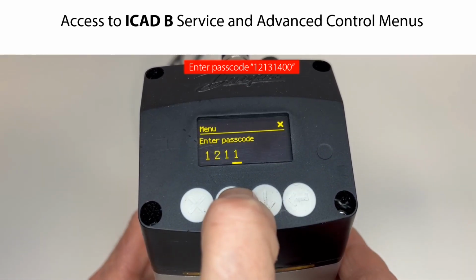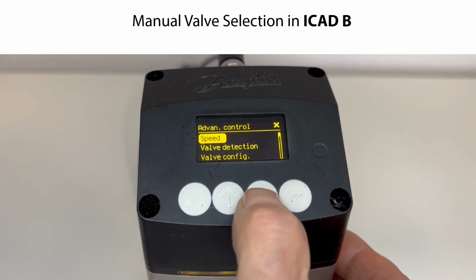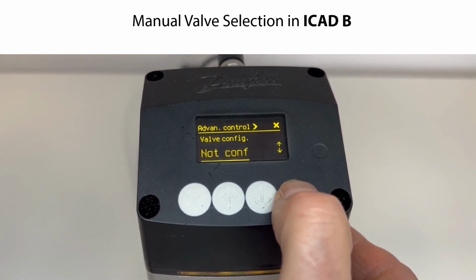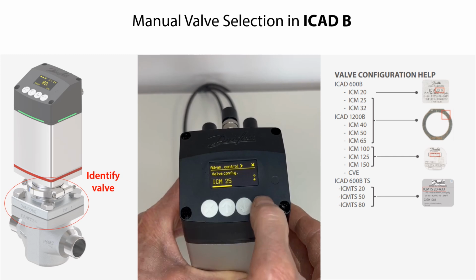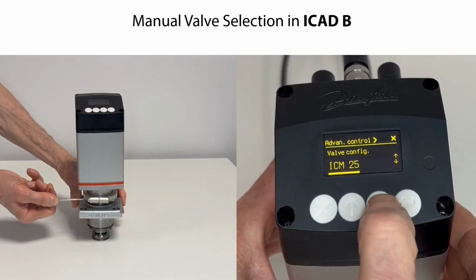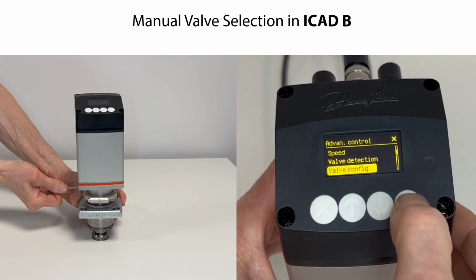If requested, then enter the service passcode as explained earlier in this video. Scroll down to Advanced Control, then press enter. Scroll down to Valve Configuration, then press enter. Select the valve type and size corresponding to the valve on which the ICAD B is mounted. Here you see illustrated how you can identify such valve. This is taken from the ICAD B installation guide. Since we demonstrate the valve selection using an ICM25 valve function module, we select the ICM25 valve. Press the enter key to confirm and set the ICM25 valve.